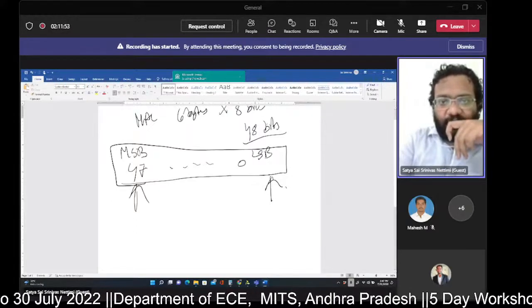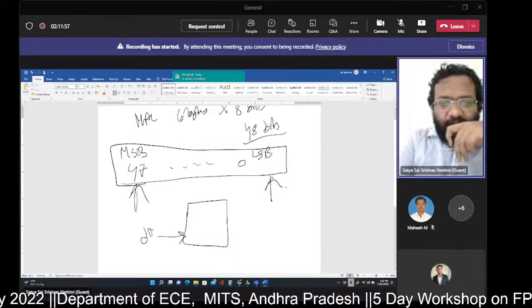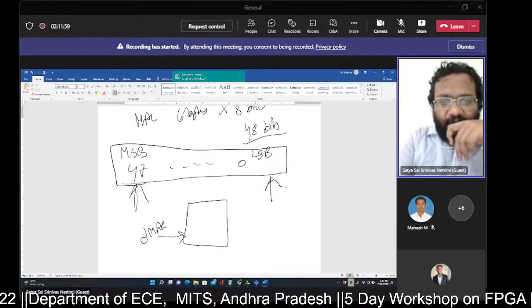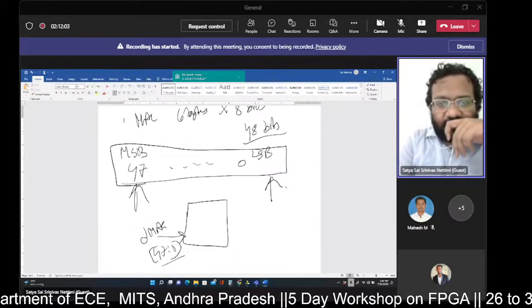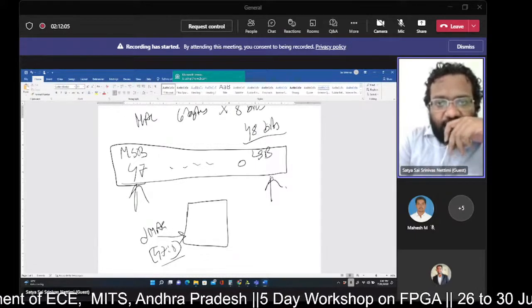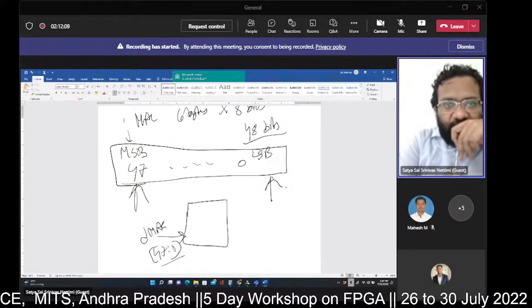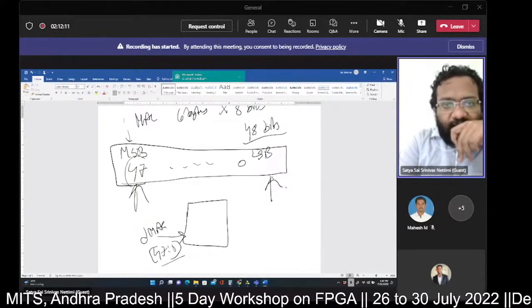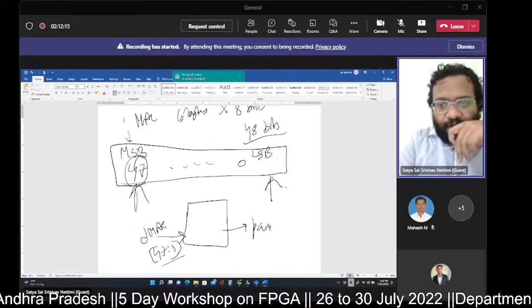And we are assuming that to our Ethernet packet generator, we have a DMAC input. From this, we are getting the input 47 down to 0, the destination MAC address. Now what we have to do is read the address from the MSB position, and each bit we have to send on our packet output.